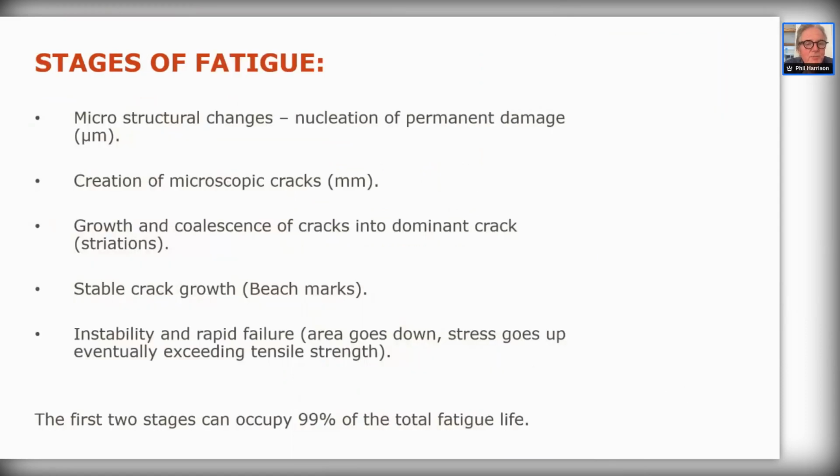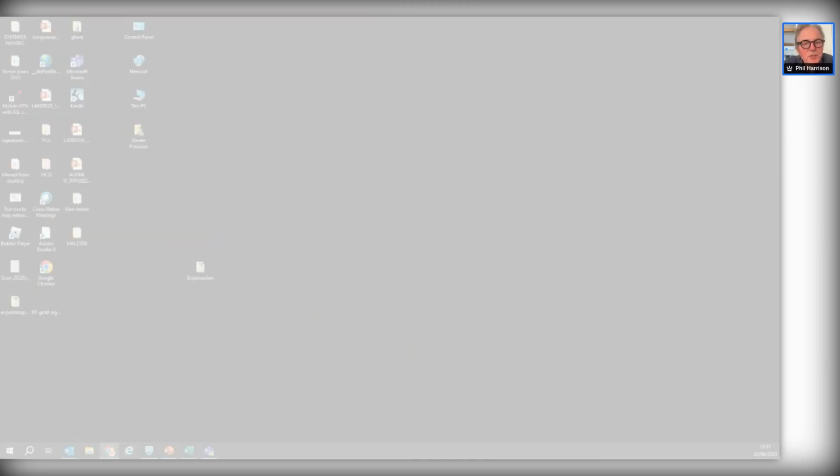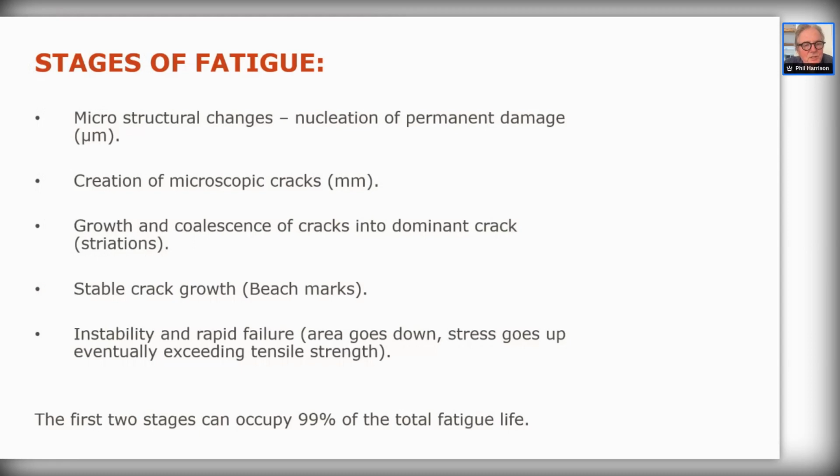And these are stages. These are where we get microstructural change in the material. This is where we start getting permanent damage. This is where we start getting buildup of stresses in the material. The stresses, very, very briefly, are strain energy built up, the creation of a crack, and the surface area then depletes the strain energy, which then builds up again, the crack extends, etc., etc.